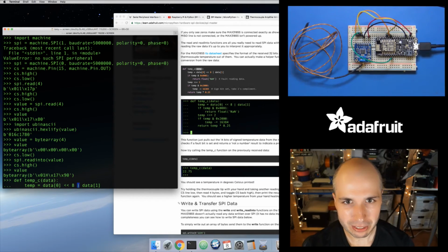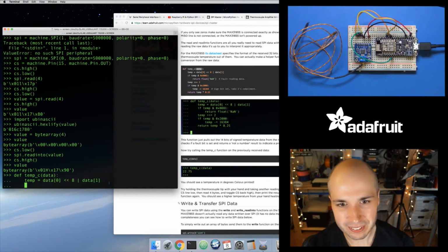It just takes 2 values, and this value right here is going to be 16 bits, where the upper 8 bits are set to some value and the lower 8 bits are all 0. Because I'm doing an OR with that, and all of those lower 8 bits are 0 on the left-hand side, it will set any of those bits to 1 wherever they're set to a 1 in the lower 8 bits. So it's just kind of jamming these 2 values together. A very common thing you'll do a million times in embedded programming like this.